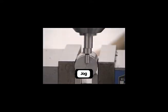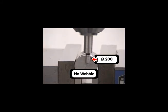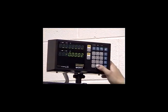The bottom section of the edge finder has a very precise diameter of 0.200 inches. So when the edge finder jogs, the part is 0.100 inches from the exact center of the quill. The digital readout can then be zeroed by pushing the desired coordinate button, either X or Y, entering -0.1 and pressing P. The procedure can be repeated for the other coordinate direction if desired.